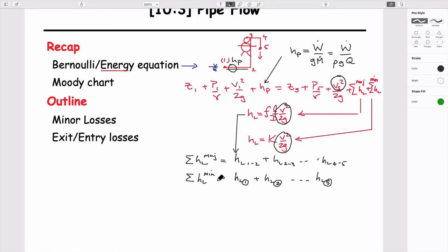And basically, I think what would come out of this, if you ignore the difference in the slight elevations, well, no. For these particular cases, the pressure where it goes in is going to be 0. The pressure where it comes out is going to be 0. If the flow rate into here and the flow rate out of here are the same, then this term and this term will cancel.